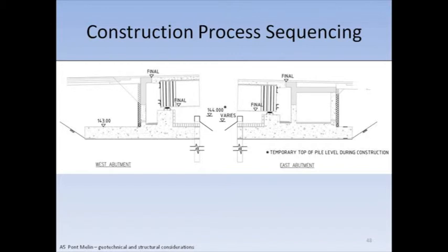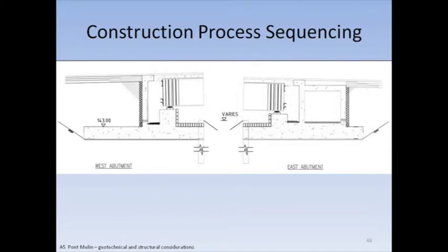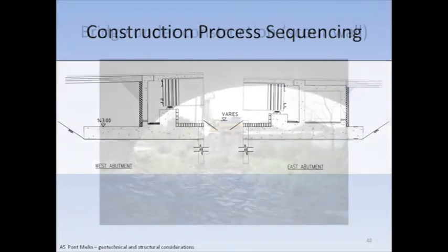The settlement now occurred, the bridge deck and its complete slab has been cast. There's been fill on the abutments for the duration of the construction as well, and the cattle underpass has been cast. So the final process would be to grout up the bearings on the beams, and then the final little bit of fill at the ends of the deck and the run-on slabs.